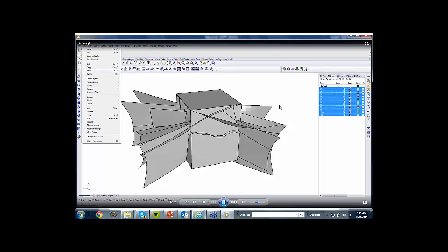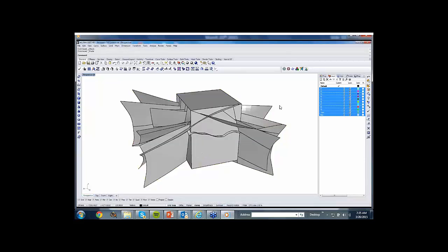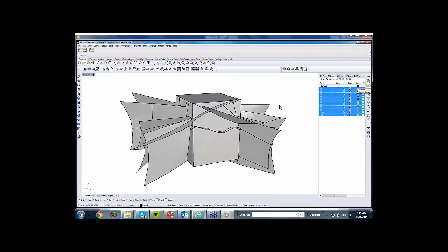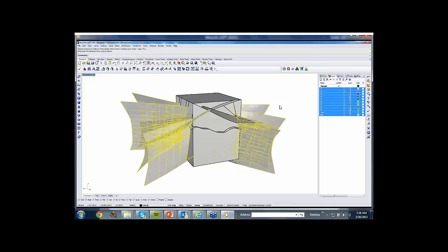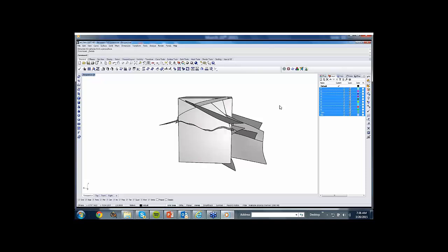All right. So as you can see, I copied the previous surfaces because the identity of the previous surfaces was lost during the merging process. By now pasting back those surfaces, they all have gone into their respective layers, and I have turned off the layers, so that information is still there. So we haven't lost the original one by doing this copy. So I go to extract surface, and I click on everything that is outside, by strategically aligning myself with the walls in various directions. I get rid of all these additional surfaces that stick out of my model.